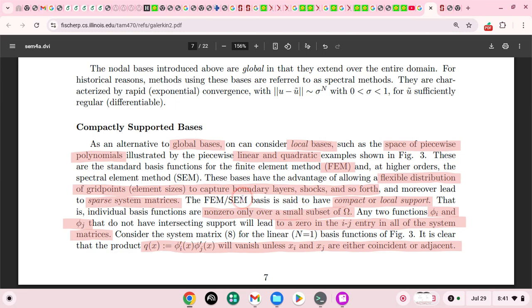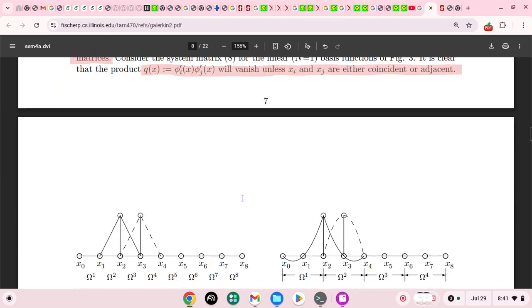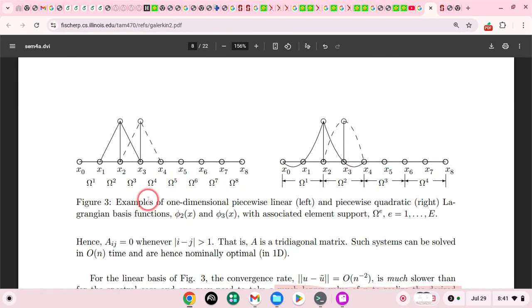And there again I can say that a basis function can be a global basis function, which will have some continuity throughout the domain, or a local basis which has only local support. The finite element method is mostly based upon local basis functions, which are defined such that they interpolate between nodes, say x1 to x3, and vanish outside of this domain.